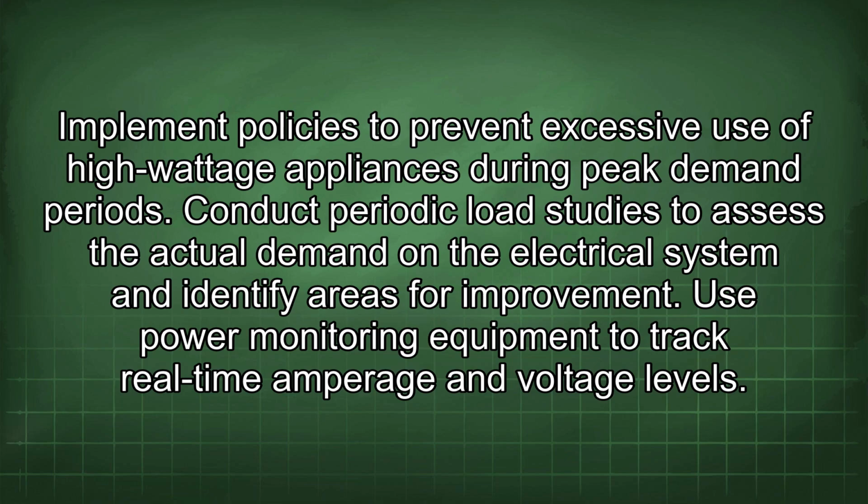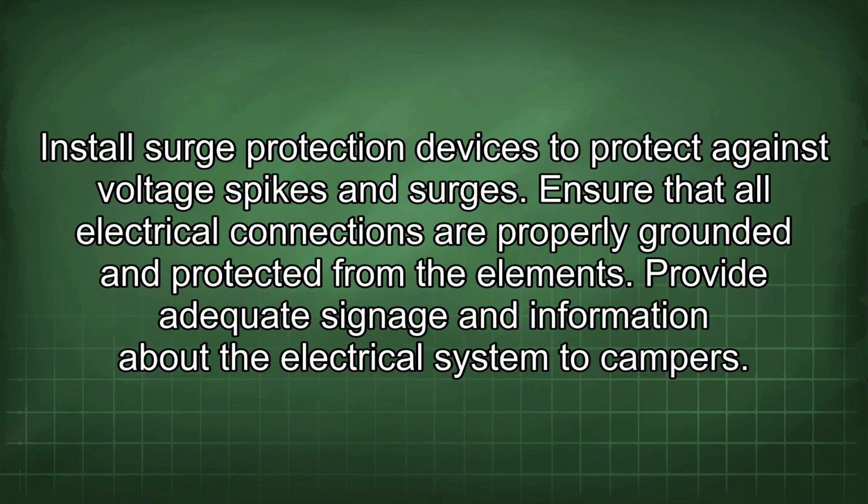Conduct periodic load studies to assess the actual demand on the electrical system and identify areas for improvement. Use power monitoring equipment to track real-time amperage and voltage levels. Install surge protection devices to protect against voltage spikes and surges. Ensure that all electrical connections are properly grounded and protected from the elements.